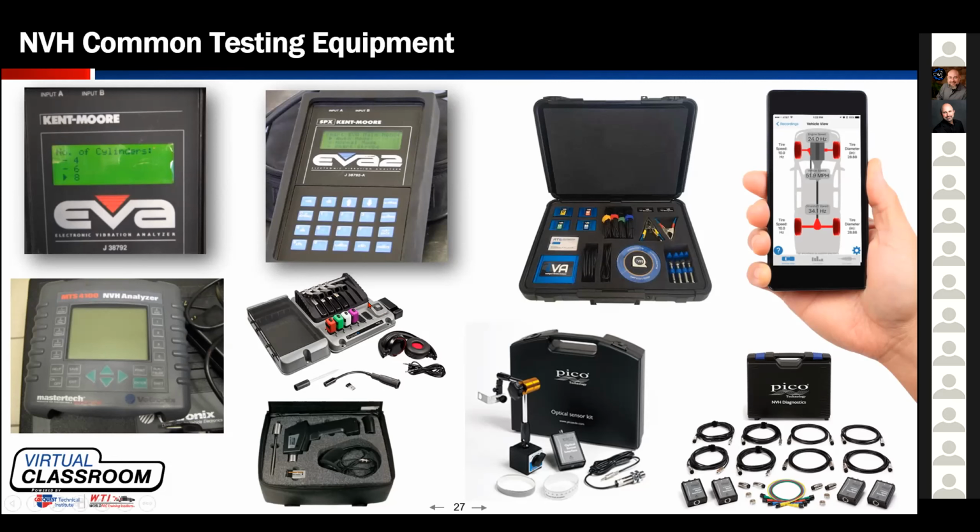Underneath these, I have two different types of listening devices. We have the chassis ears. Guys, chassis ears have been around a long, long time. They have the wired versions, they have the wireless versions, they have the Bluetooth versions like this. But the idea is you can put these clamps on the car and listen to the noises and pick up the possible direction of where they're at.